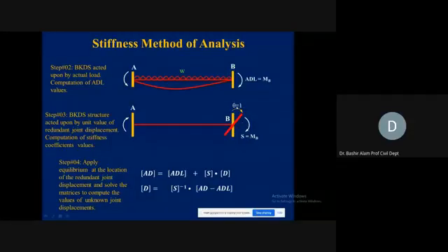This is because of the unit displacement, so we multiply by whatever actual displacement we have in order to create the actual moments, and those moments will take care of the moment produced here, and this way we can put this system in equilibrium. So AD is coming from the previous slide, ADL will be coming from here, and S will be coming from here.